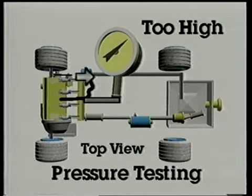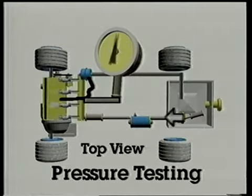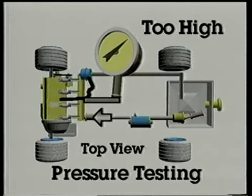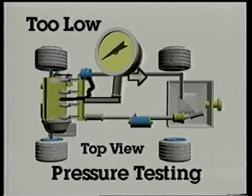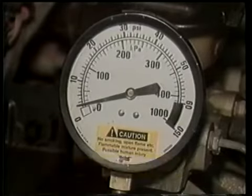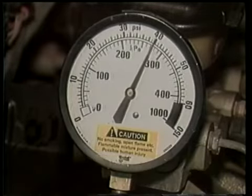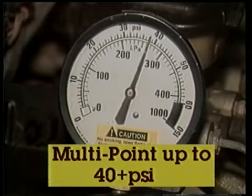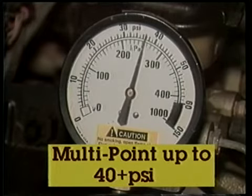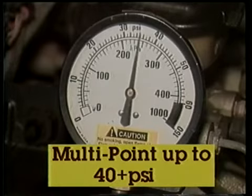A clogged filter, bad fuel pump, leaking fuel line, sucking vacuum, stuck pressure regulator, or smashed return line can all be detected. If pressure is too high or low, or if pressure bleeds off too quickly, it gives you hints about what might be at fault. Typically, TBI systems have lower pressure. Multi-point systems have higher fuel pressure, but remember, always refer to specs for exact values, since the pressures can vary considerably.